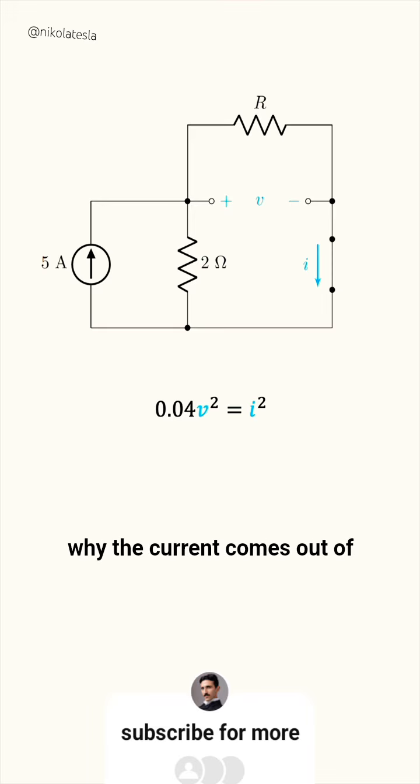Here's why. The current comes out of the 5 ampere source, reaching this junction. Part of it goes down through the 2 ohm resistor, but the remaining part goes up through the R resistor, and this is exactly the labeled current I. So, by applying Ohm's law, we see that V must be equal to I times R.